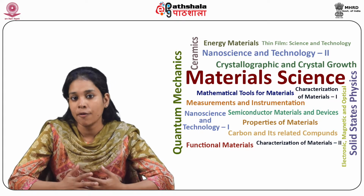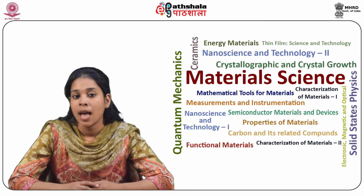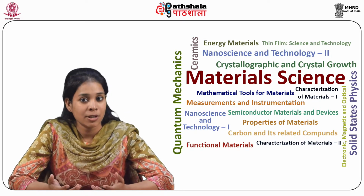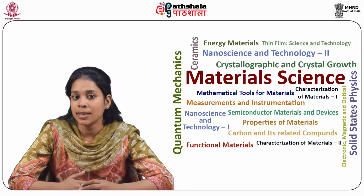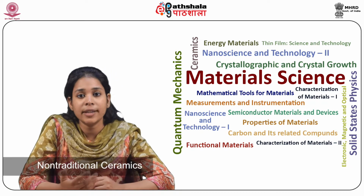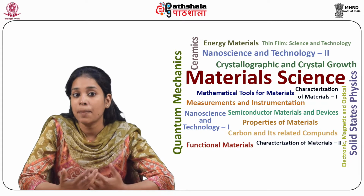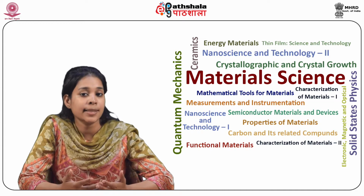A majority of ceramic products are manufactured using liquid phase sintering, and most of the traditional ceramics we have discussed earlier, such as sanitary wares, tiles, etc., have siliceous liquid phase present during sintering. Some examples of non-traditional ceramics are ferrite magnets, covalent ceramics such as silicon nitride, ferroelectric capacitors, tungsten carbide with cobalt for cutting tools, etc.